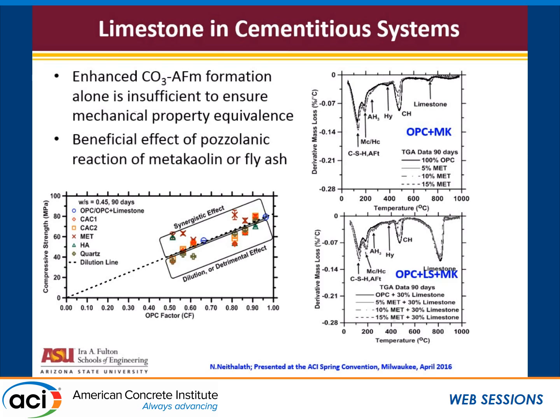Okay? So you have calcium hydroxide in the system because of cement hydration. Your metakaolin or any of those pozzolanic materials will eat up your calcium hydroxide, but in the process of formation of this carboaluminate, the monocarboaluminate case, so this is with just OPC and metakaolin, look at the amount of calcium hydroxide when I replace with 15% of metakaolin. But when I have 15% of metakaolin, 30% of limestone, look at that calcium hydroxide content. This was here. This is here, the scales are the same. So now you see suddenly your calcium hydroxide dropping with increased amounts of limestone.